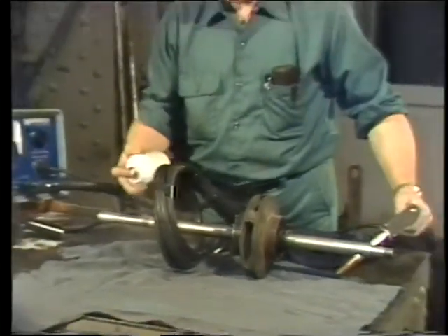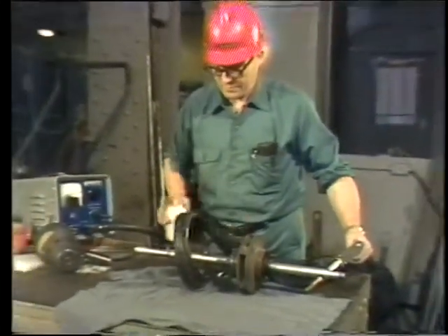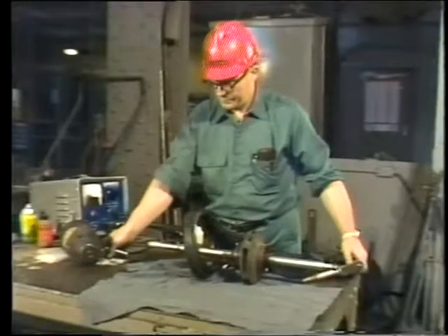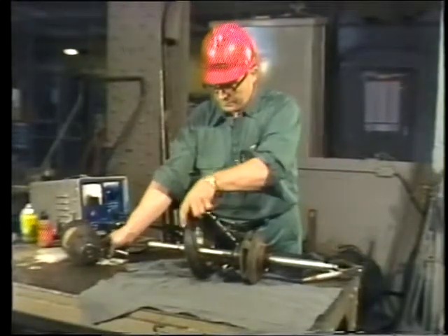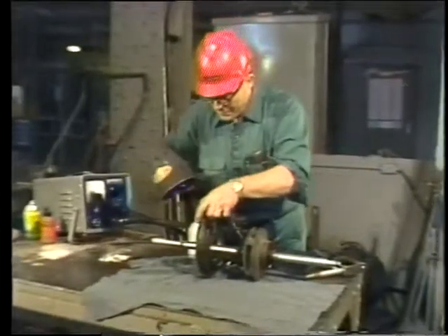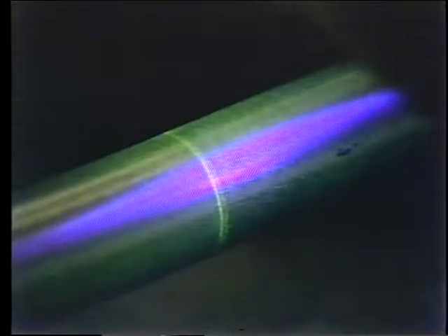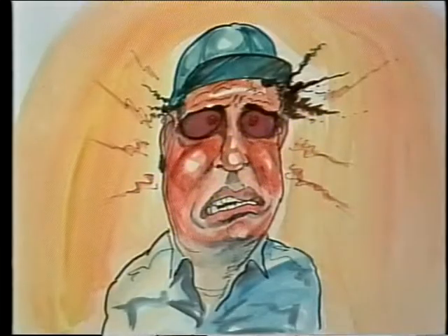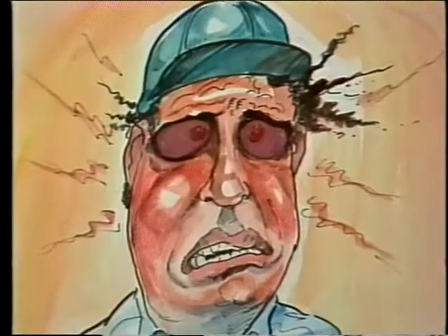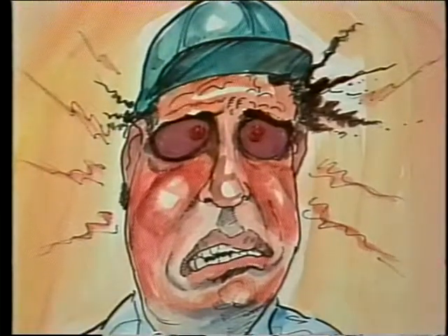Some kinds of liquid penetrants and mag particle tests can also be hazardous to your eyes. The methods that use black light to make fluorescent dyes or particles show up have to be handled carefully. Black light is really filtered ultraviolet light, the kind of light that gives you sunburn. The filter protects you somewhat, but if you're careless enough to look directly into the light, you can literally sunburn your eyes and cause permanent damage to your vision.